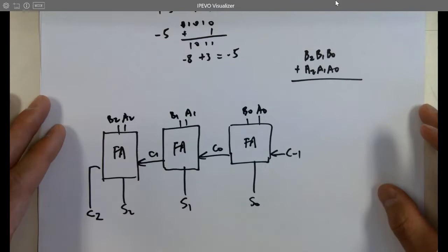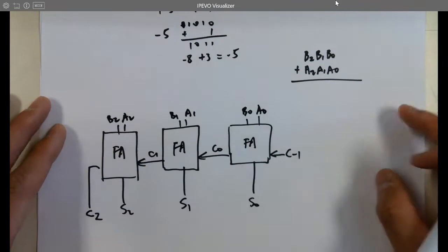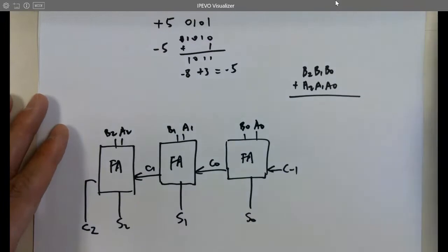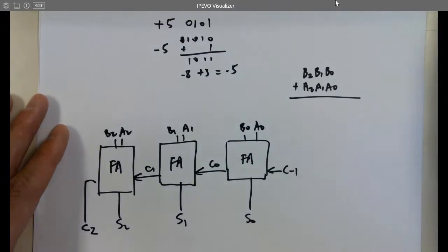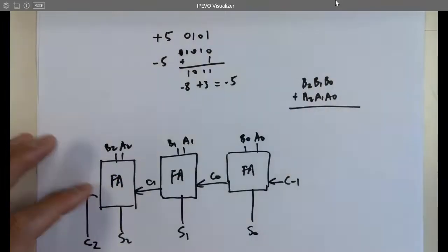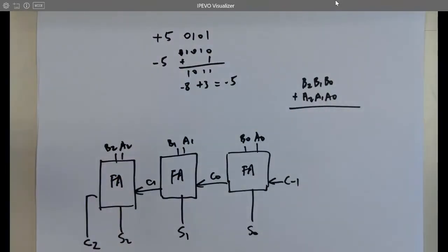All right. So it's definitely the adding operation. How do we make a subtraction from that? The design is really interesting and smart. Not inverted, but you need to plus one as well. You have to invert it and then plus one to make it a negative number. So when you are doing addition, it's actually subtracting that number.